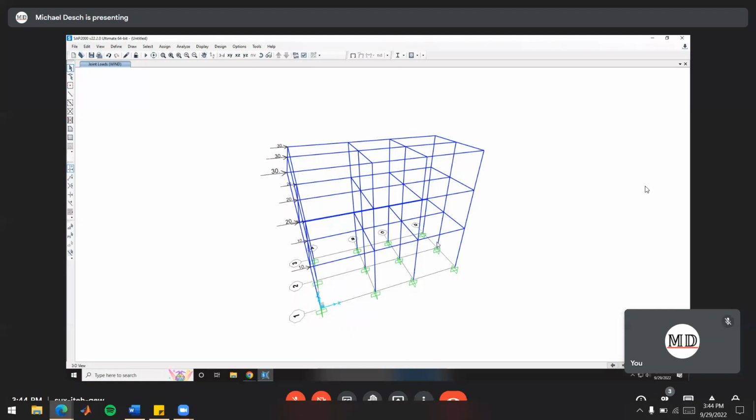Wonderful. Okay. One last thing. Not that we need to do it for this model, but it's a useful tool you might want to know about. Up in the toolbar, you see there's this pair of sunglasses. This is called perspective toggle, and this switches the drawing style from a 2-point perspective view to some type of orthographic view.